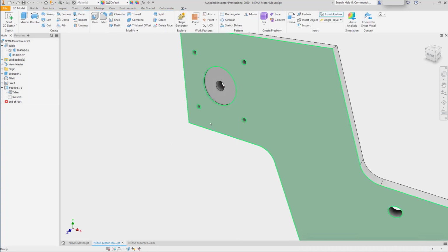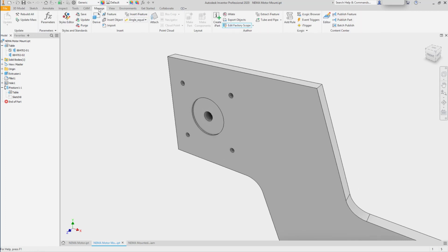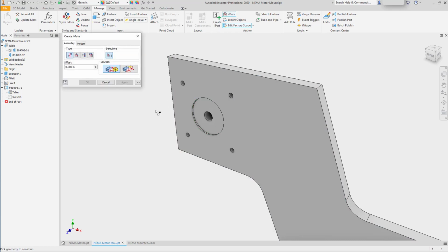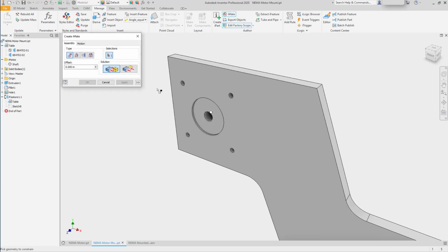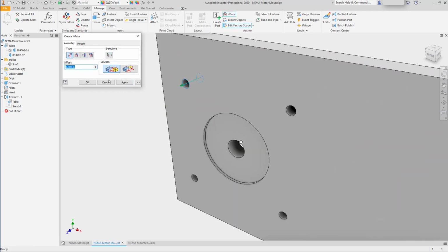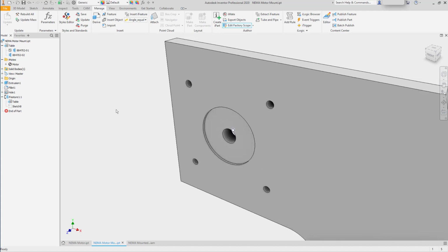Clicking Finish Sketch, it will update the location of the motor mount. On the Manage tab, I'll start the iMate tool again and recreate the steps that we used before with the motor by creating an insert constraint named Shaft, and it's important that you keep the naming the same, including capitalization, and a mate to the axis called Screw, creating a composite named Motor.